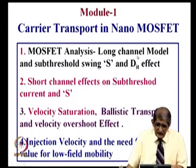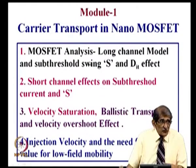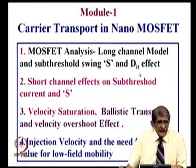I was informed that the DIT effect on subthreshold slope was not covered in the previous presentation, though the DIT is discussed in great detail. Then short channel effects mainly on subthreshold swing and current. Very briefly we will touch upon this.